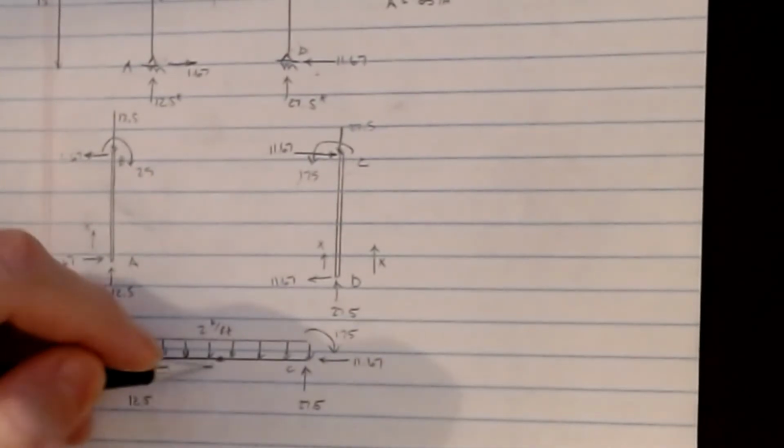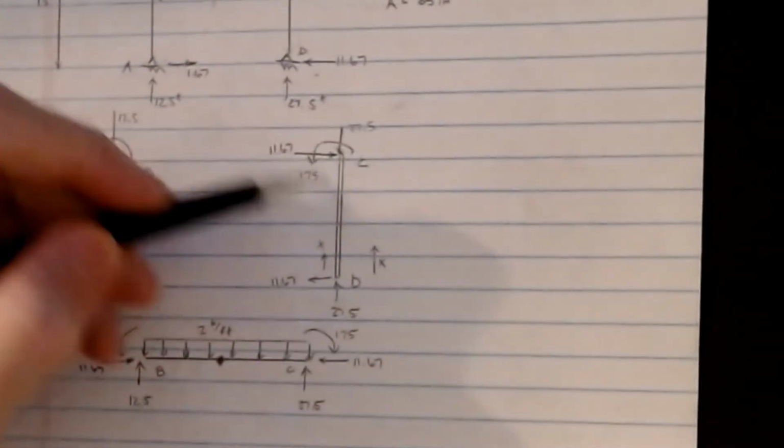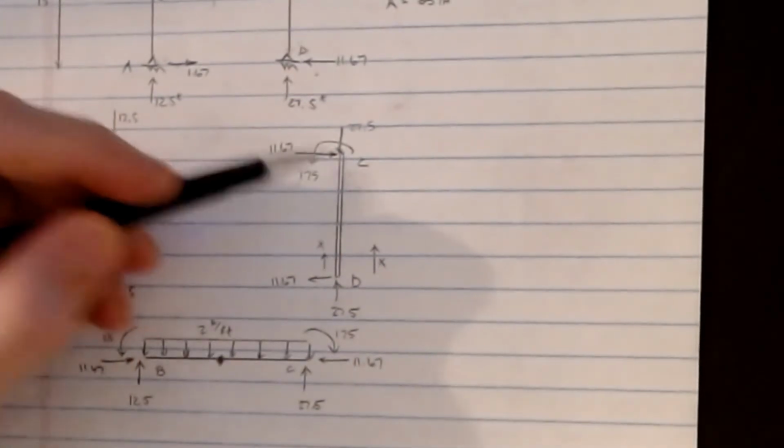All right, and then we can go through and we can draw the diagram for the beam. Now again, I've chosen not to separate it at the hinge. No particular reason. It's just you don't need to. Why make my job any more complicated than it already is? Okay, and so if I have a 2 kip per foot load acting downward at this location, and I plug in all my values, again, all of these reactions here have to be opposite of what's at the top of the column, and all of these have to be opposite of what's happening at the end of the beam also. So that's where all these values are coming from, is from these values at the top. Okay, and so we've got our basic picture. From this, you can now go through and draw shear and moment diagrams, and you can write equations for the pieces accordingly. Okay, but that's the real system.